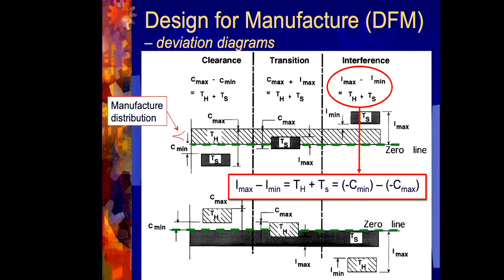And by the way, I've just repeated that. Don't forget that this tolerance zone is all about the fact that we're producing thousands and tens of thousands of the same part, and we're going to get a range of sizing. And that range of sizing, we would hope, has its mean in the middle of that rectangle, and we move out in a 6 sigma style, where as we get towards the extremes, we get very few components. And I talked a little bit about that in the first lecture, the statistics of manufacture.